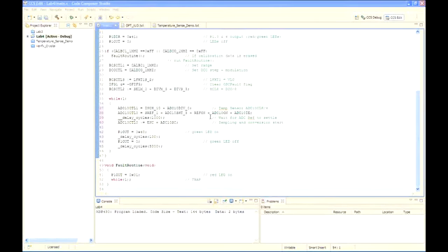Selection of the ADC10 clock is made in this register and can be the internal 5 megahertz oscillator, the A clock, the M clock, or the SM clock. The ADC10 oscillator is the default oscillator after the power up. So let's go ahead and use those settings. If you take a look at the ADC10 control 0 equals SREF1 and so on, the second line that we put in there, SREF1 selects the range from VSS to VREF. That's ideal for the temperature sensor. ADC10 SHT 3, the sample and hold time, has the maximum sample and hold time. Again, that's ideal for the temperature sensor.